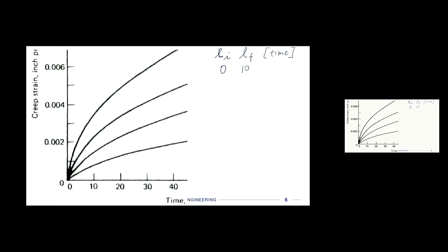And then we know we've already calculated what our strain increment for that one will be. I should have laid this out on the slide first here. Okay. So that's going to be in hours. And then we'll have our incremental creep strain, which was 8 times 10 to the minus 4. Okay, that doesn't change. Our first phase is the same for all of these.